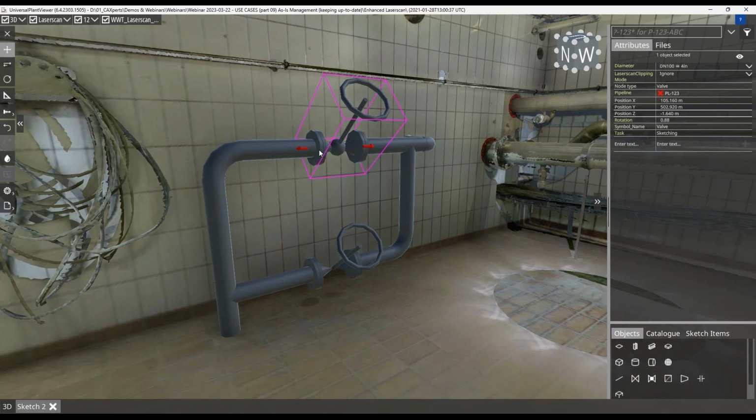What other effect is there? If we save it away as a DGN file, you can send this easily to your EPCs as an owner operator and say, okay, we have added this to our model, but please use this as a reference. Basically, put a reference into your authoring system, remodel this with the proper pipe class, give us the isometrics and things to pull the documentation straight on both ends.